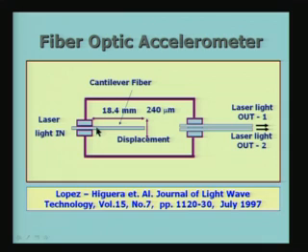So, what will happen is, if I subject it to vibration, the free end will start going up and down. If the free end goes most down, it will communicate more to the lower fiber and less to the top fiber. Okay. Therefore, if you take these two laser outputs and look at them, they will oscillate, they will change in time. So, the displacement of this will create a difference between these two signals, and therefore, whatever information I have here in terms of the frequency of vibration will also be the frequency at which this signal will oscillate. Okay. And that is the basis for this particular method, and it is a very simple instrument.